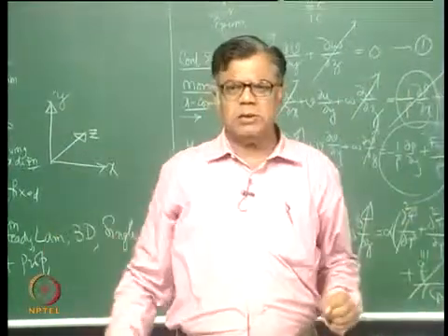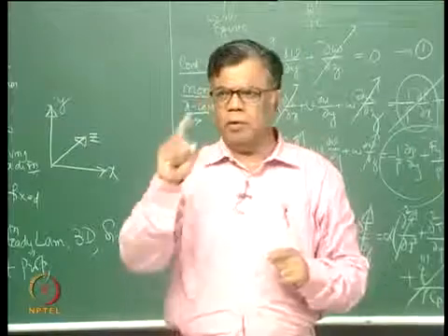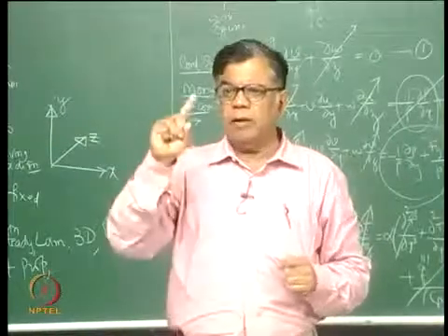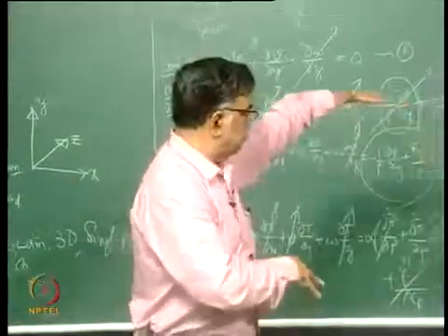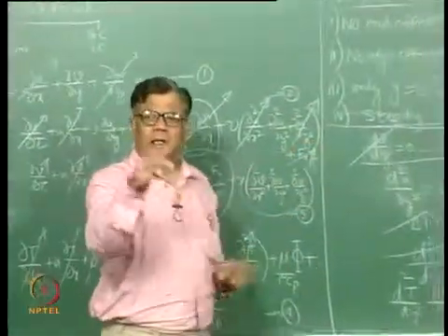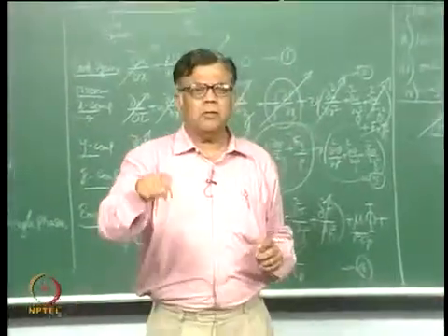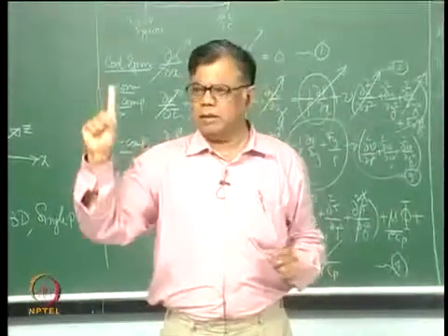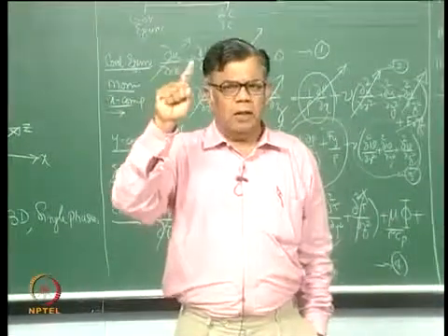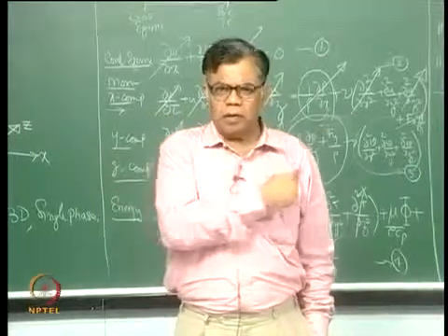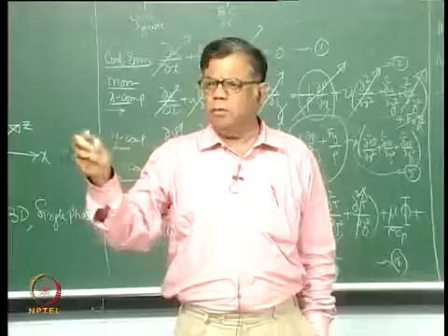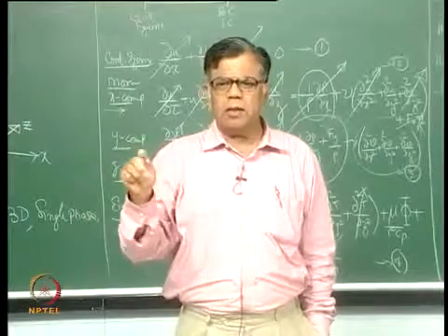Please put the boundary conditions at y = 0 for u, v and T. At y = 0, T is T0. Now the equations are completed. The mathematical model is not complete till you write the boundary conditions. Please write the boundary conditions. At y = 0, u is 0, v is 0, we have given the reason why it is so, and w is 0, T = T0.